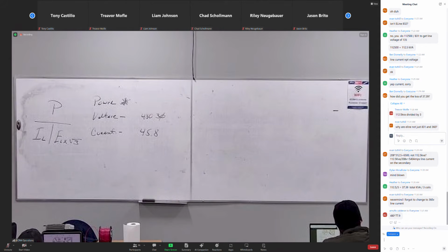What do you guys get? 38.07. Would you get that? Right, close enough. It depends if you take it all the way out on the square root. Don't forget, it's three-phase voltage. You have to multiply it by 1.732 because it's line voltage. Line current, line voltage. Even though it's only one leg, it's line.